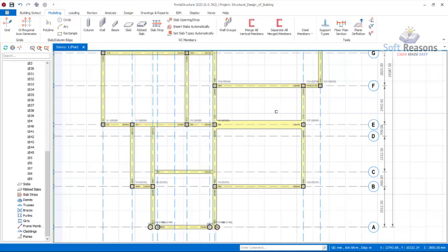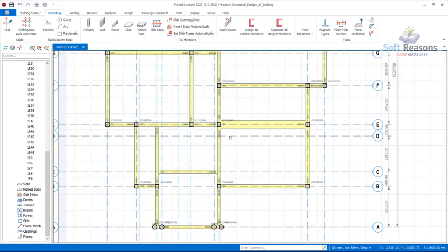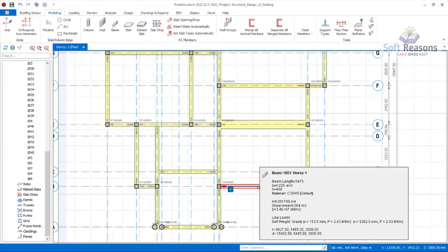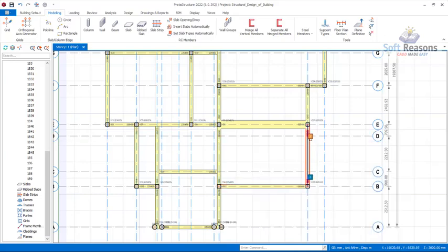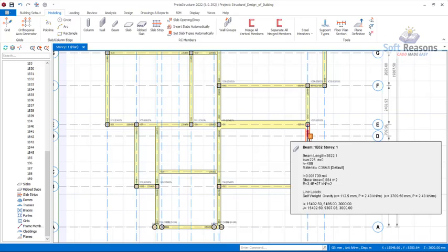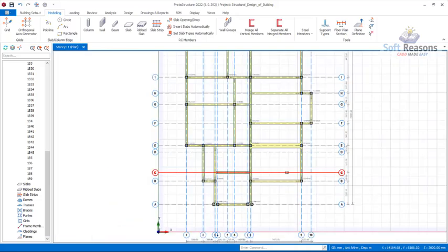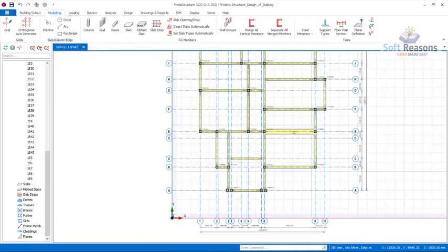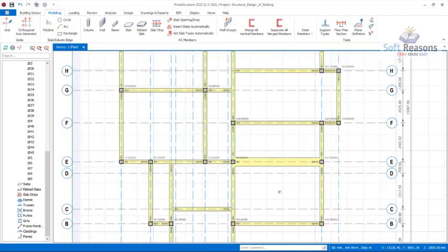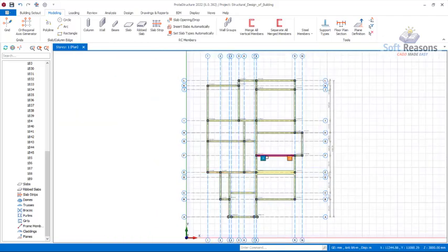Anything more than 30% of your reinforced concrete slab area should have a concealed beam introduced. When I say area, you multiply the length, which is about 5 point something, by the width, which in total should be about 6 point something, including this. Once you multiply that area and it gives you something more than 30%, you have to introduce a concealed beam, which is what we've done here, so as to avoid reinforced concrete slab failure and also deflections.